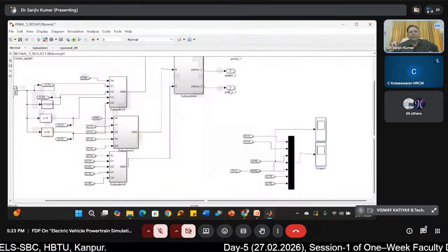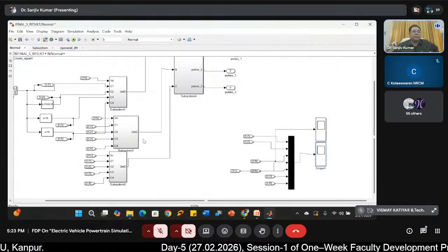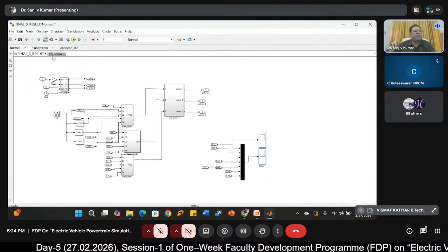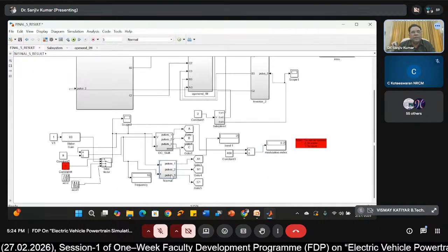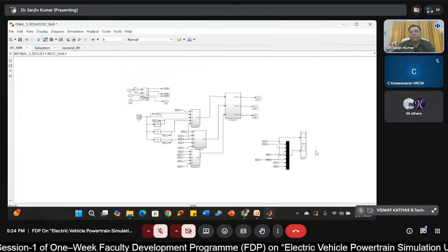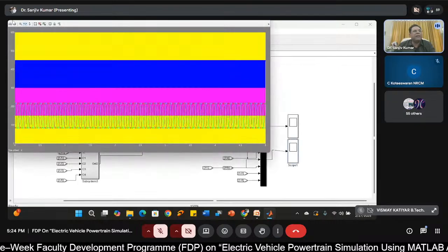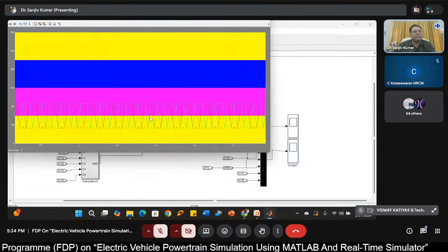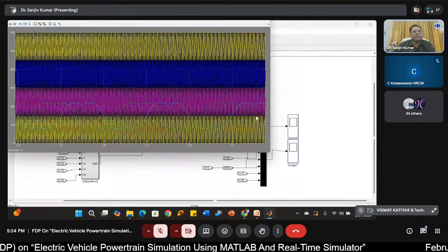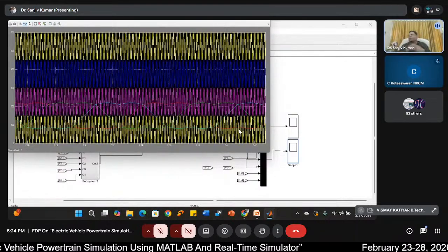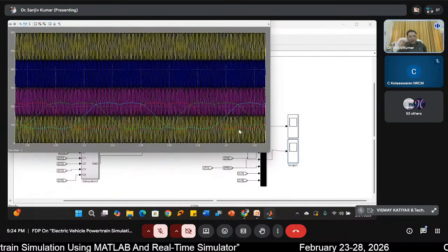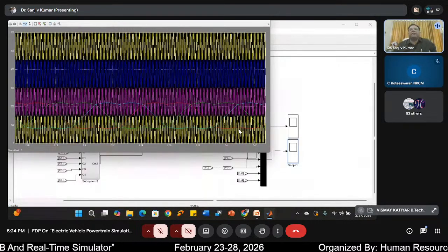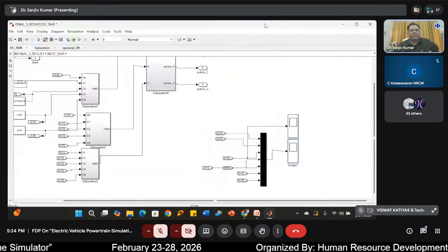But in the topology, the switching or control algorithm which we have developed, we use this DC shift algorithm, and here you see it would be at the bottom. Look at this, it is at the bottom. The advantage of this is lower switching loss. The inverter which has a higher DC link switches less. That is the advantage, so inverter efficiency gets improved.